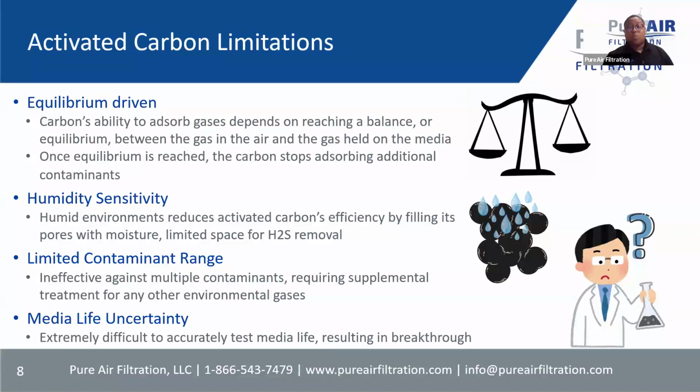Activated carbon also works well for organic molecules. So that's going to be any molecule that contains a carbon atom. For H₂S, obviously, that's just hydrogen and sulfur, so it's not going to perform as well. It works better for larger molecules as well, so that's going to be molecules that have a higher molecular weight. H₂S has a low molecular weight compared to other molecules, and so it's going to be struggling to compete with those larger molecules for space on the pores of the activated carbon.